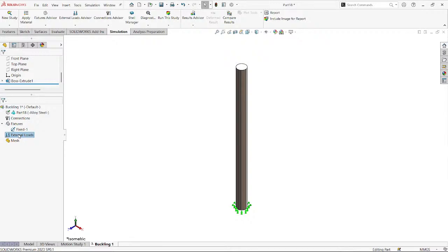You need to remember the load, whatever I'm going to apply here, is not going to matter for me because it's just a unit factor here. I just want to extract the buckling load factor. So to get the buckling load factor, I need to have the unit value here. The value I should define as 1. If I multiply 1 into BLF, I'm going to get the buckling load factor. So whatever the critical load I'm going to get will be visible with respect to this analysis.